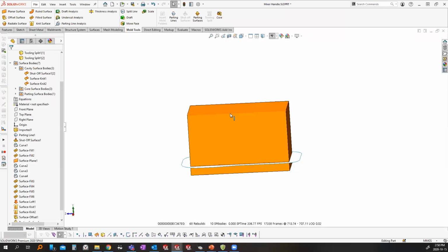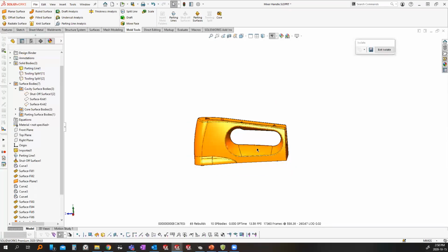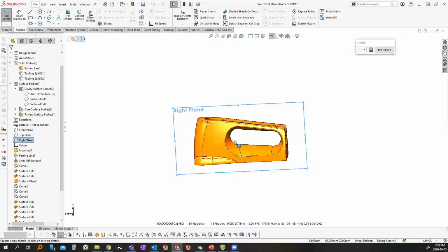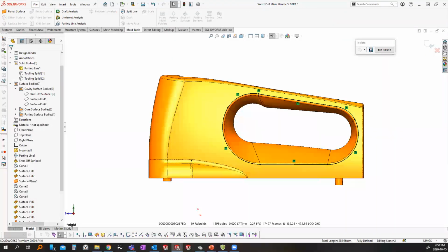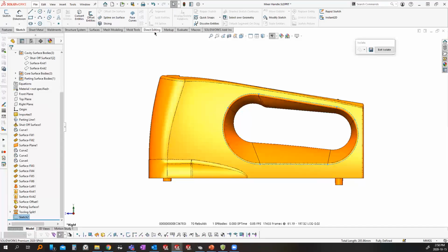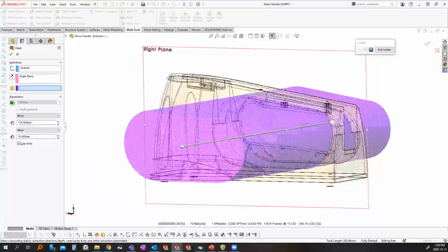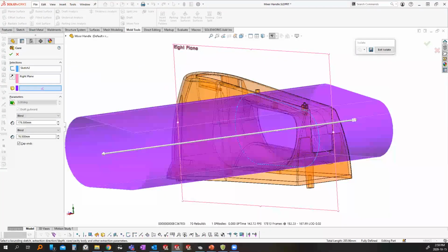Now this isn't going to be manufacturable because of the handle. Right, we have this big hole in here. Typically I'd use the core command, but to use this command, if we go inside of it, we would typically come in here. I could grab some geometry, convert that, and use that to create my core. So this would attempt to develop my core. The only problem is it needs a body to end on, and I have open space, so this is going to fail, unfortunately.